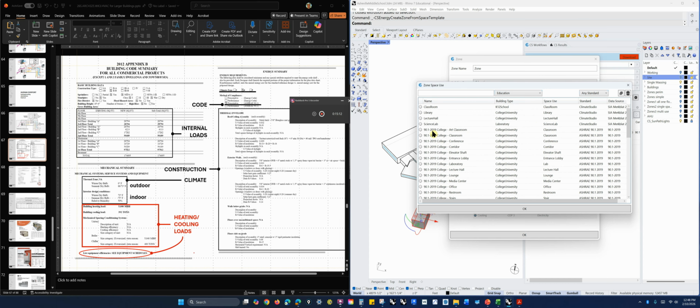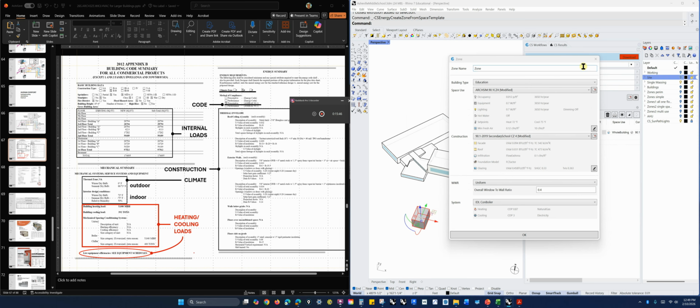And so these are zone templates, right? What if we said a zone is, a thermal zone is simply a box of air that has specific heating, cooling, ventilation requirements relative to another box of air that's next to it, right? And so it's going to have different requirements for our HVAC system based on where it's located, the people that are using it, the equipment inside it, etc. Okay, so we can choose a template that relates to our situation. So I'm going to get out of that.